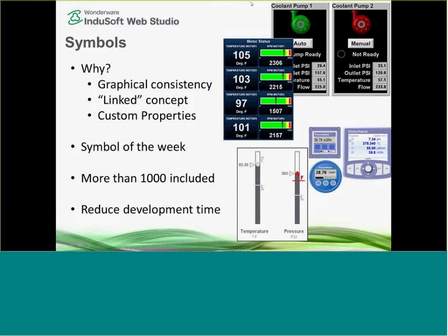And if you put the pump 2 symbol on the screen, that'll go back to a second symbol. If you wanted to change the pump 2 symbol in all the different places you used it in your project, you can go back to that one linked design, change it, and it will change all the instances of pump 2 throughout your entire project. That's really handy, really nice. So there's that linked symbol concept.